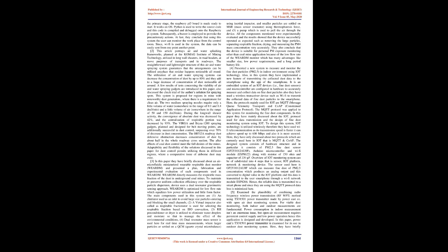The main components used in this system are: 1. An elutriator used as an inlet to avoid large size particles entering and blocking the small channels. 2. A virtual impactor, also called a respirable fractionator, used for selecting the respirable fraction based on the ISO convention. 3. An RH preconditioner or dryer, utilized to eliminate water droplets and moisture so as to manage the effect of